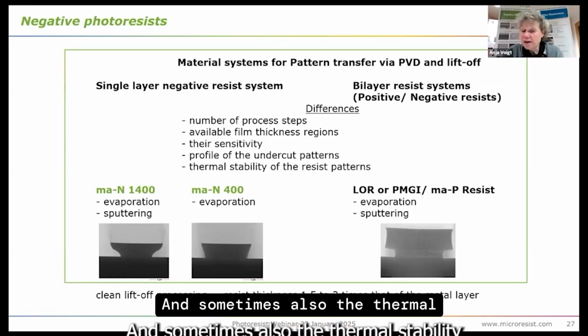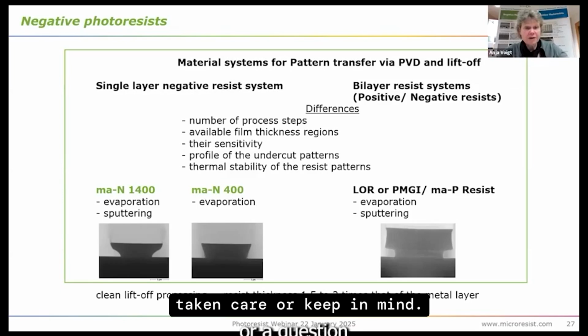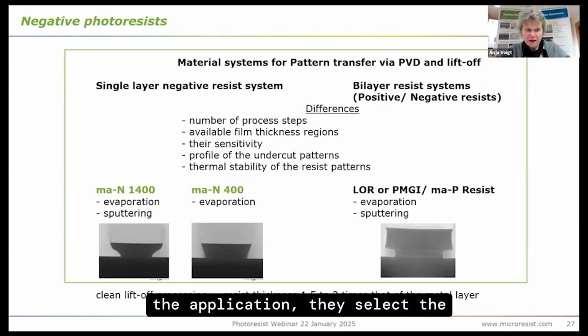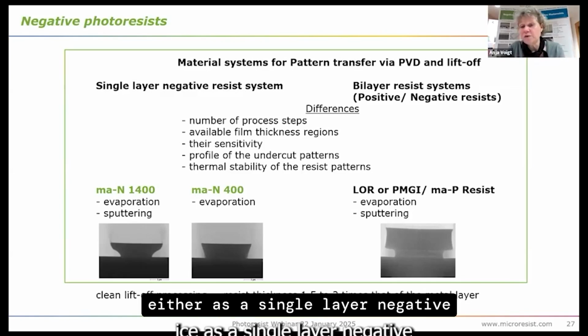And sometimes also the thermal stability could be an issue or a question the customers have to take care of or keep in mind. And according to the requirement of the application, they select the right material, either the single layer negative or the bilayer process.